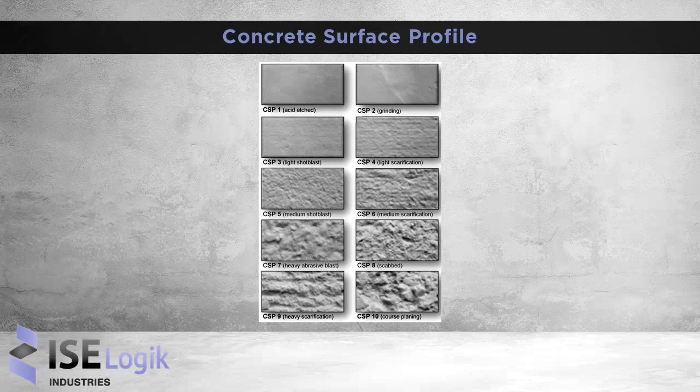And recently, in the past couple of years, there's been a new ASTM for porosity testing, and that is ASTM F3191. I think quite a few adhesive companies and topical cementitious companies are referencing the ASTM F3191 test for testing for a porous or a non-porous surface. And we have a number of options too on our porous versus non-porous products, and what needs to be done if it's a non-porous surface.